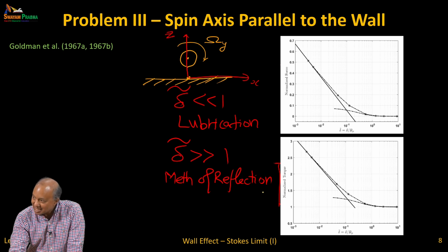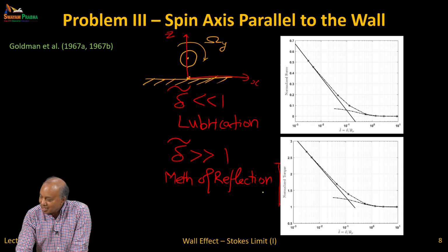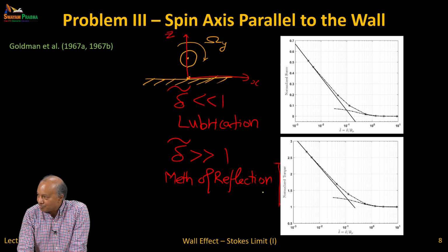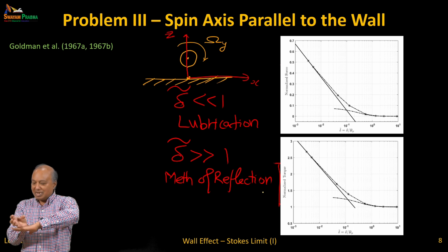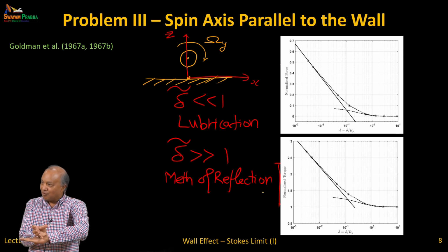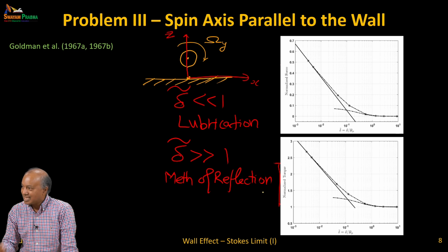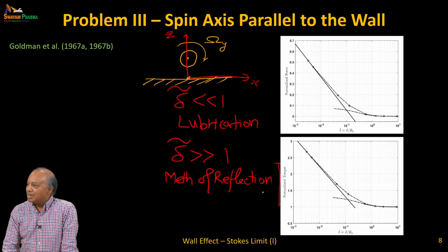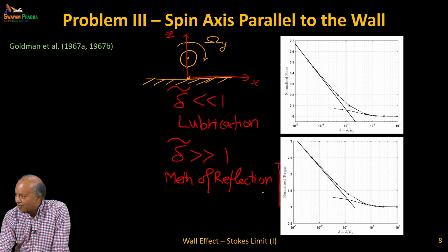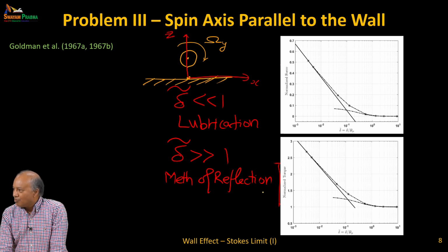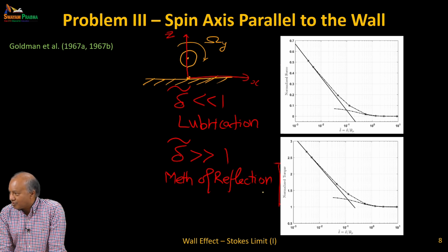Depending upon the type of shear, any kind of shear, it will have to roll, because the cost of sliding is tremendous. Because sliding means the particle has to displace the fluid, the thin layer of fluid, it has to squeeze out. But rolling is a better way of it moving. So the answer to your question is, if you have a small particle close to your wall or sitting on a wall, a rough wall, and you apply any kind of shear flow, it will tend to roll and move forward rather than slide and move forward.